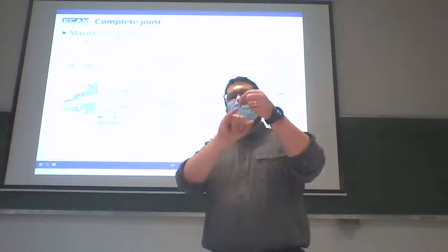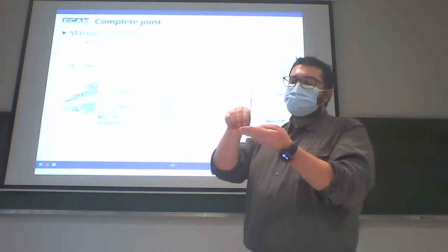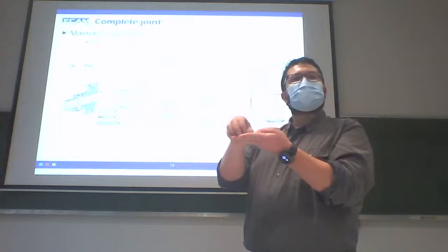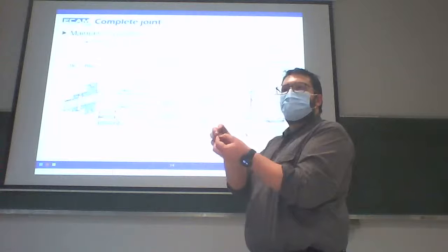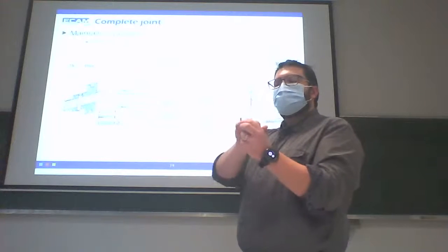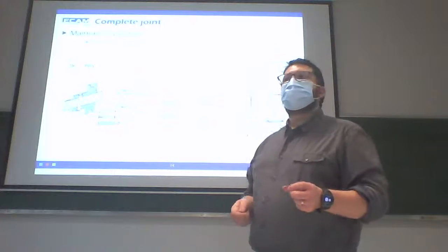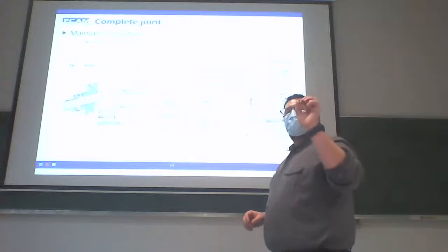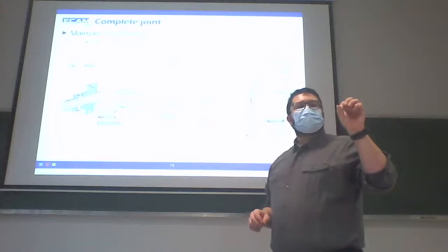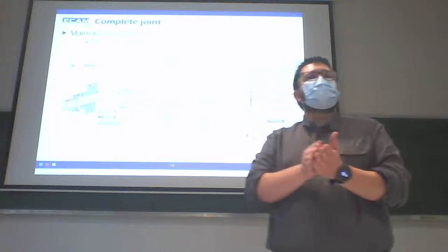One side of the pin has a chamfer to facilitate the coming of the pin inside the hole. Okay, it's easier to put the pin if we have a chamfer. At the opposite, we have a round. Okay, you can use a hammer to hit the pin. A cylindrical pin just fixes the position, but does not maintain it.